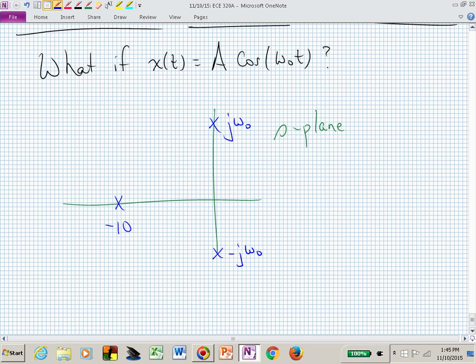It just keeps shaking. So what would you think you would see at the output? I just keep shaking this system. What do you think you're going to see at the output? The same shaking, right? That's the only thing it can do. What you may have is a transient. You will have a transient due to that pole at minus 10, but eventually your system is just going to keep shaking. We'll figure out what it does with that shaking on Thursday.